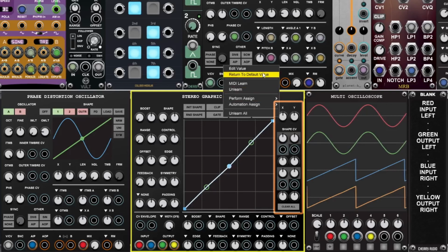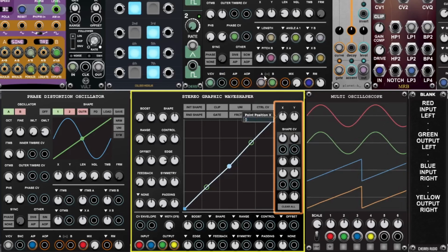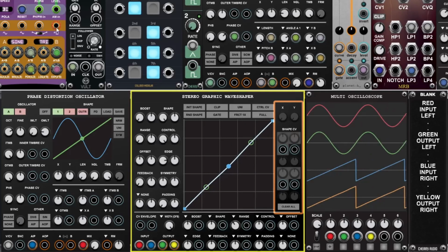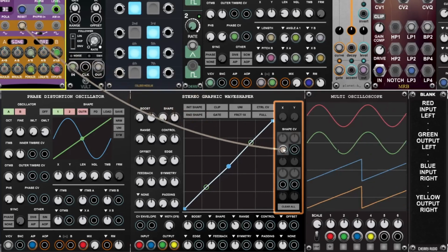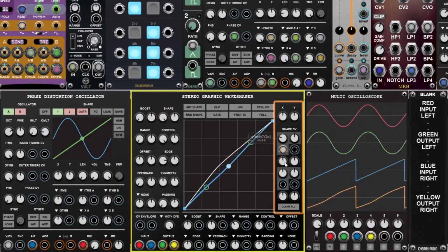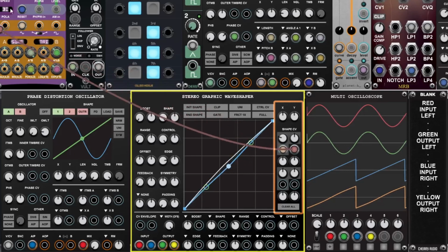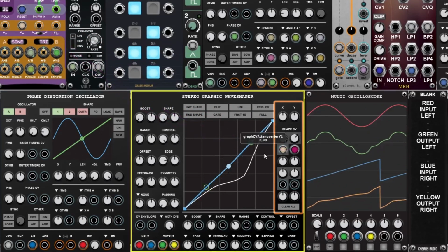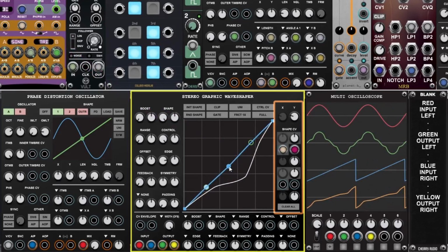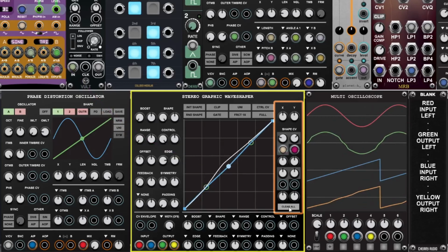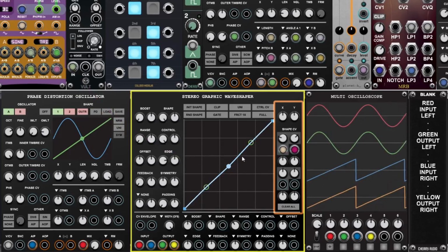Furthermore, the CV inputs below enable us to manipulate the shape using control voltages. Each input jack has related X and Y attenuators. You can identify the corresponding knobs by the color coding. When you want to apply modulation to another point, simply select it by clicking on it in the display. The X and Y knob values are saved per point and can be edited again when you select the point again. On the bottom, there is a handy button that clears the X and Y knob values for every node, thus effectively erasing all applied modulation.